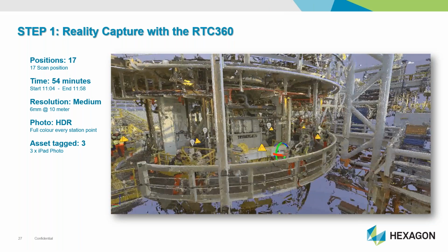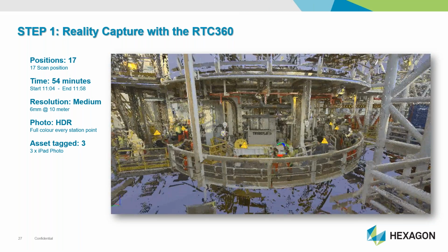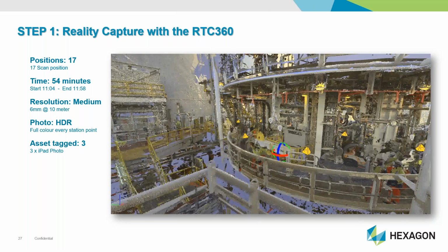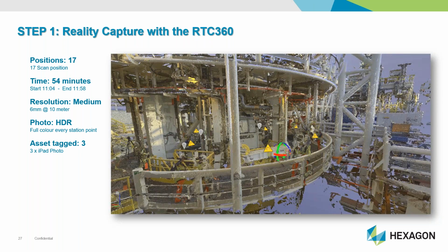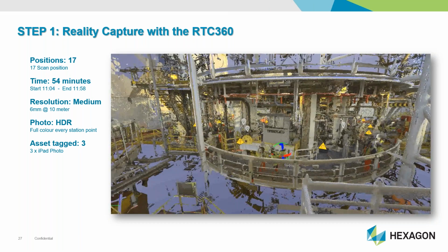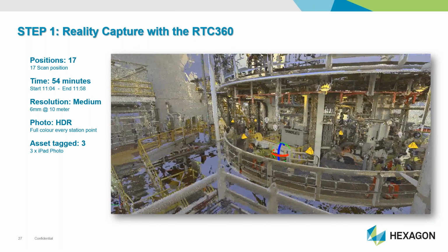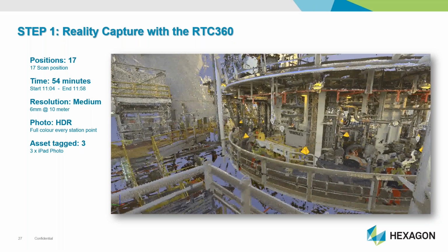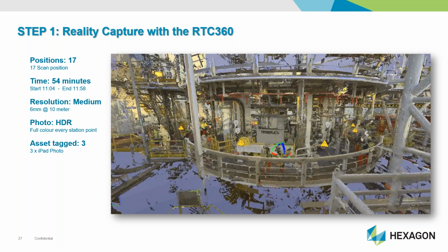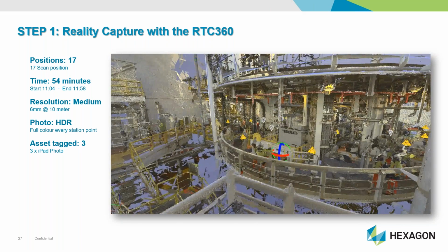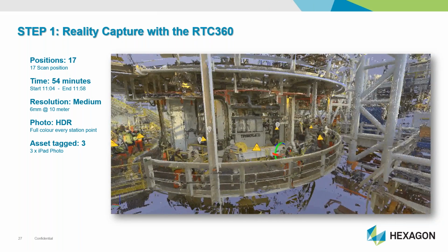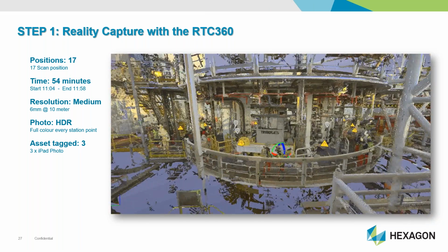So, reality capture with the RTC 360. This is just a very, very small job. What I will make a point of saying here is I'm not advocating not using targets for these types of jobs, but we can if we want to. We can use Viz and our registration on the tablet to do it. But with a lot of these jobs, we will typically be using a Leica total station to fire in control points on spheres or black and white targets to tie this to an existing control network and also provide repeatability and redundancy. You can do that process all in software if you need to.